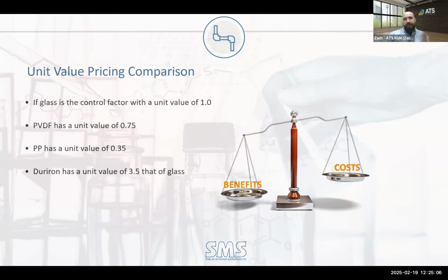And then, continuing on, right. If you're doing new construction, you can do a combination of these, right? Correct. Absolutely. So to reiterate the sprinkler, non-sprinkler, because there was a special provision added to our code to allow polypropylene for this application, if that criteria is not met, it doesn't have sprinklers, then you do have to comply with the flame and smoke requirements of that non-combustible structure.